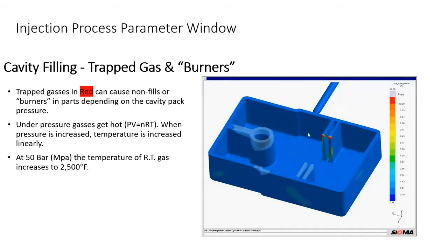Those are non-fills, scorch lines, knit lines, defects that will definitely need to be designed away from in the DFM portion of designing cavities. And as we see, this is a single runner. If we look at multiple cavity performance, this adds much complexity to the design of a multi-cavity mold. Okay, so I kind of gave you that run through.